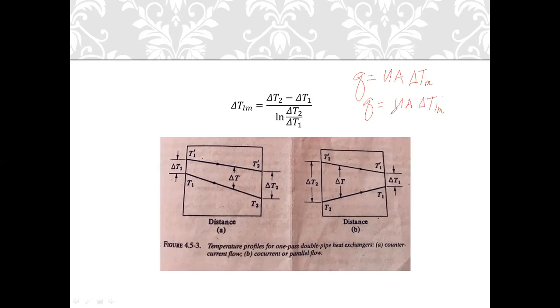Now, especially when we talk about heat exchangers, in which you have a bundle of tubes or two concentric tubes, you have to change the delta T mean, which we have been using and accustomed to at the start of the topic, to delta T log mean, so that we can account for this varying temperature difference profile for your fluids flowing inside the pipe and outside of the pipe. I think I have overly emphasized that already.